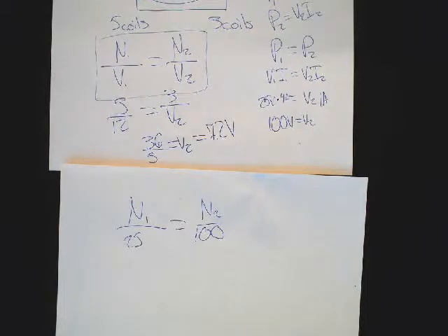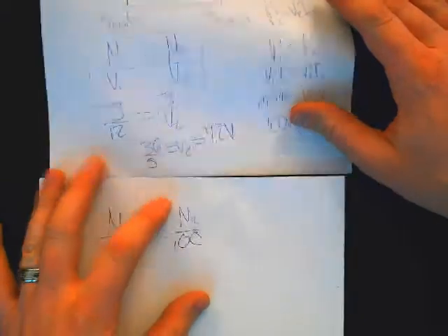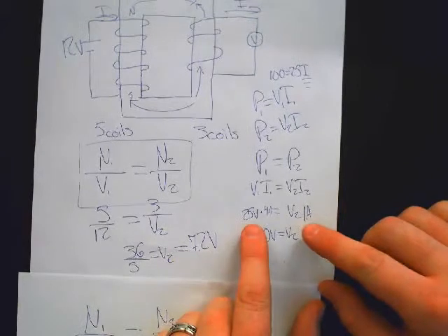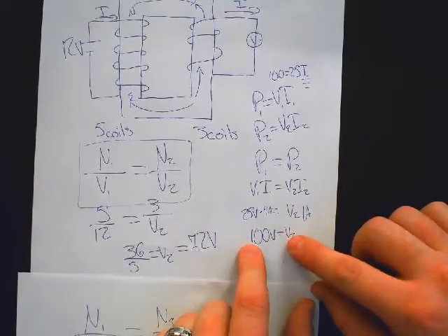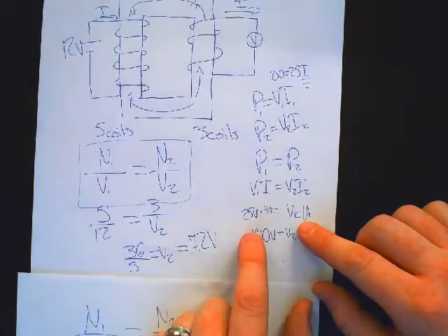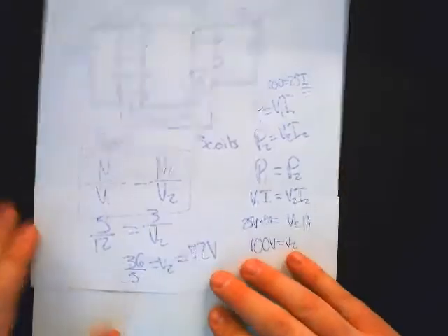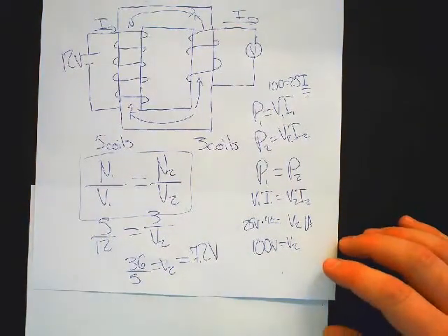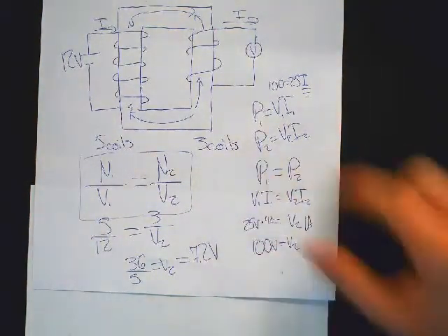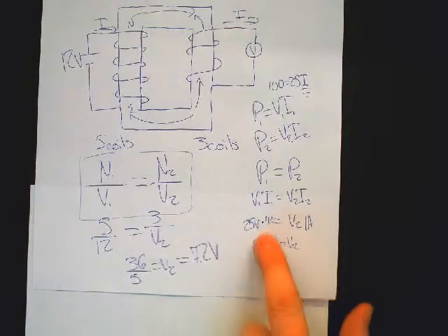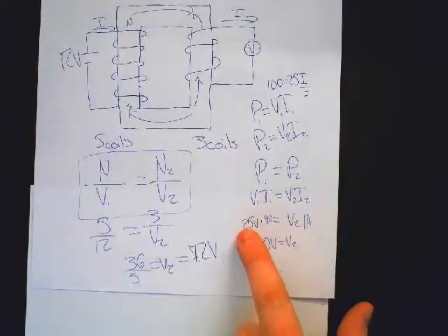And number 7, you should also be able to figure out because we just talked about power in a couple of situations here where if we have a higher voltage, meaning like a 100 volt scenario, something happened to the current. So is something stepped down when voltage is stepped up? You tell me. We totally looked at an example here. I mean, that's reasonable because I went from a 4 amp to a 1 amp. That was stepped down when 25 went up to 100.